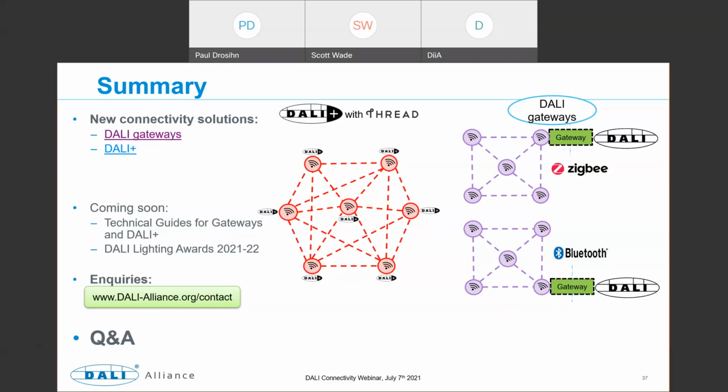But a native DALI Plus device, such as shown in the diagram here, would only have DALI Plus certification. There's no DALI 2 certification required. It will follow all the tests for the implemented parts of the standard for DALI Plus. So if it's an LED driver, parts 101, 102, 104, because it's DALI Plus control gear, and then 207 because it's an LED driver. So yeah, I think that answers the question. Yeah, I think it does.